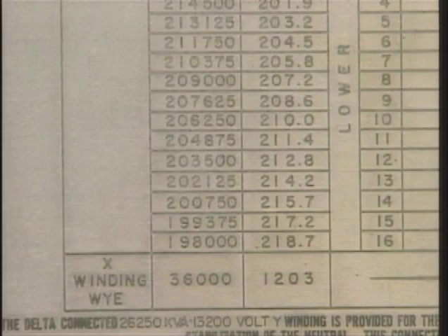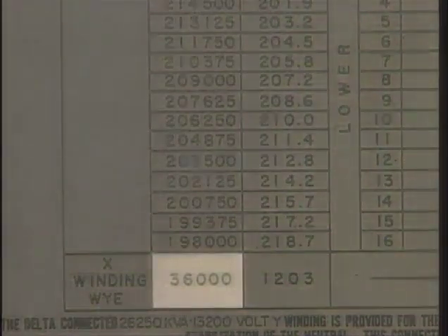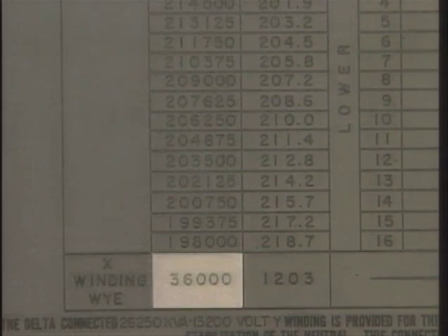As indicated on the nameplate, the low voltage winding rating is 36,000 volts. This is the low voltage figure that would be used for this transformer in the turns ratio formula. The ratio that you get on the turns ratio test set is compared with the calculated expected ratio. Depending on your company requirements, a difference of anywhere from plus or minus 1/4% to plus or minus 1% may be acceptable. Be sure you know your company's maximum acceptable difference.